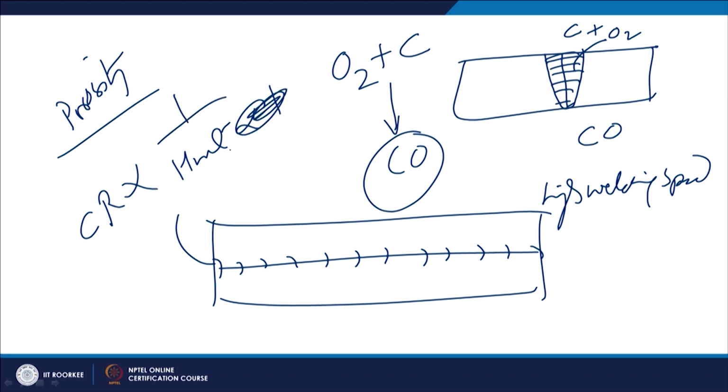So, if the heat input is reduced, this in turn increases the cooling rate. There are two aspects: the faster extraction of heat from the weld metal, coupled with the higher cooling rate due to the higher welding speed.